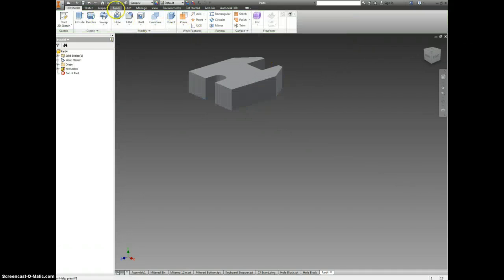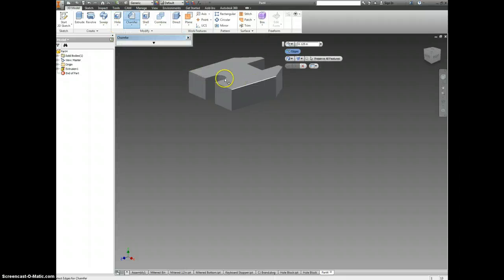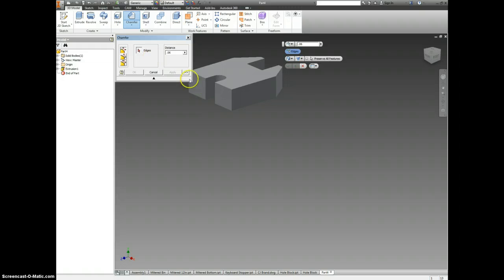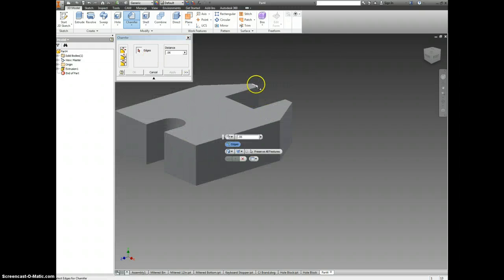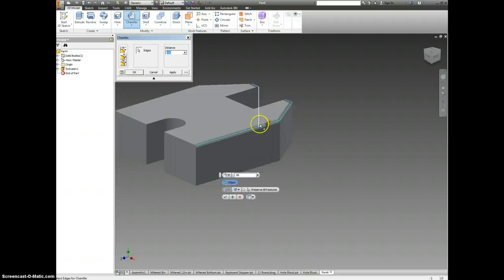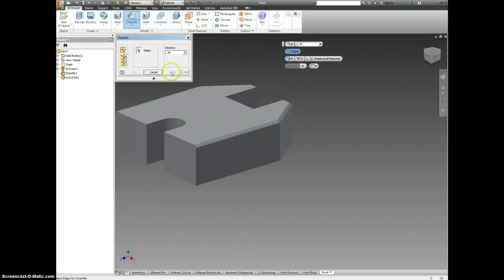We're going to add a chamfer. Where did they hide that from me? Here under fillet. So add a chamfer of 0.06, and that's going to go on not all of the edges, but these two front ones and the sides here. Apply that.